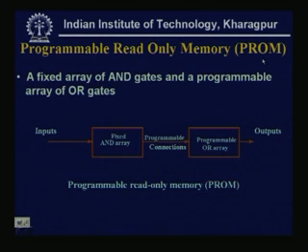The structure is that we apply the inputs to the fixed AND array, and the AND array outputs, through programmable connections, go to a programmable OR array and give the outputs.